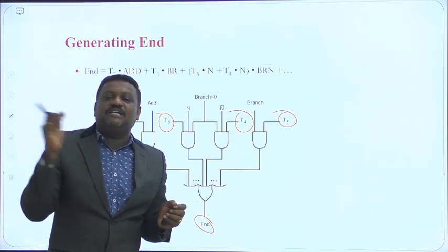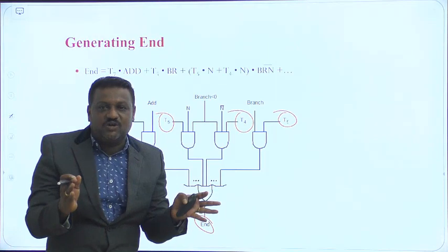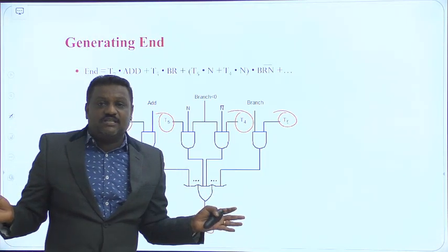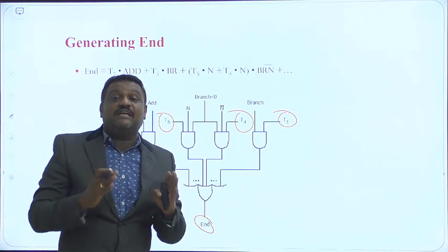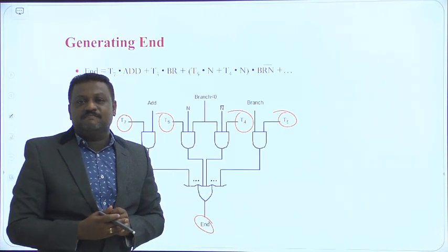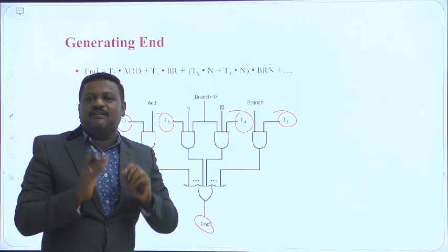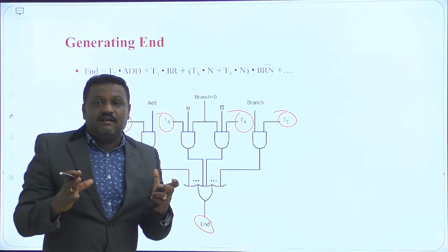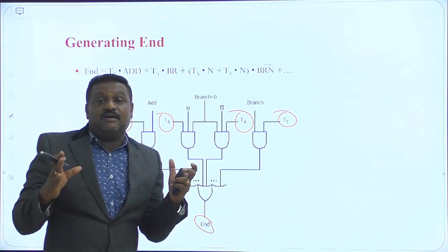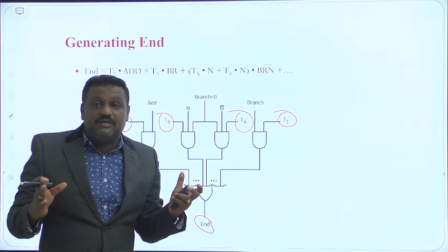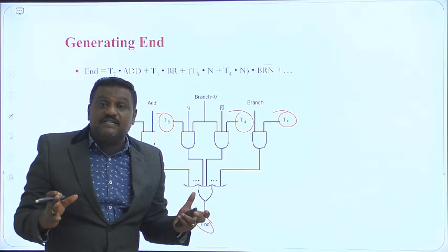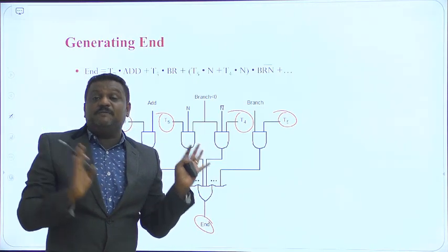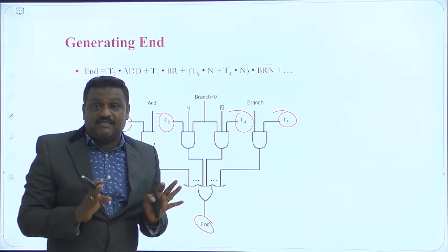For generation of each and every control signal there is a dedicated circuit, so with dedicated circuits for generation of control signals, the control signals are generated at a faster rate. At the beginning of this concept, I told you that by the end we could easily see why the hardwired control unit is a high speed control unit, as well as less flexible. So one thing is very clear, friends: the speed of operation of the hardwired control unit is fast.